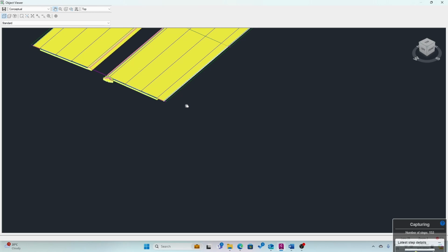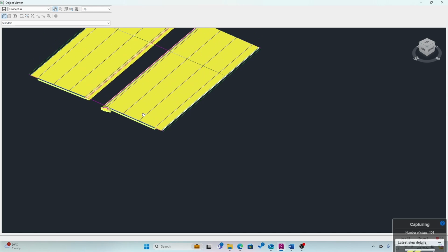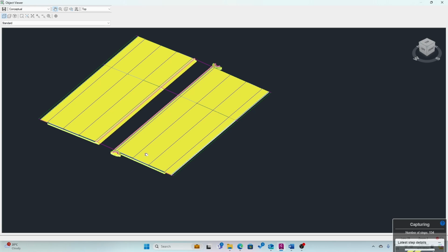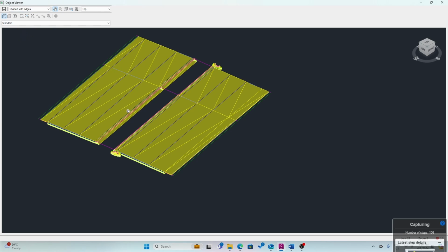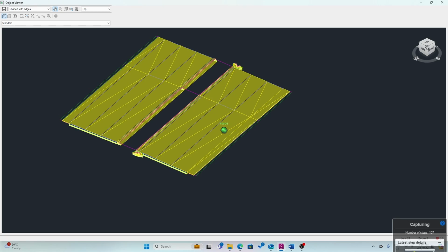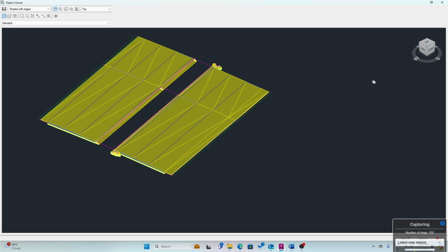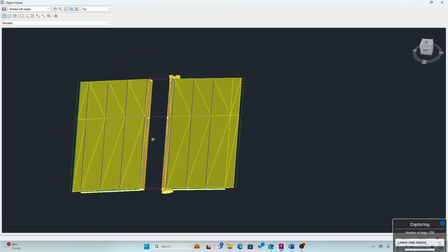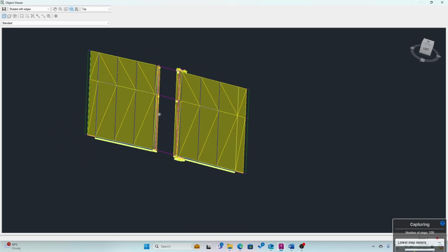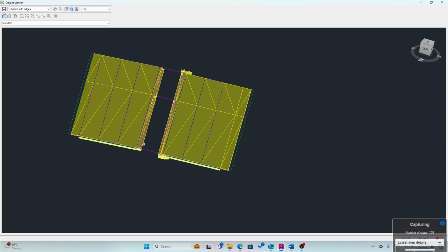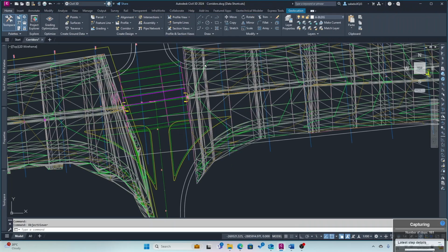We begin to see that our corridor is beginning to model nicely, but what we just need to do now is some targeting so that we are able to tie the lanes up nicely. Beginning to look nicely, our corridor, and here's the bullnoses. We need to bring these lanes to come closer. Okay, we can get out of this.